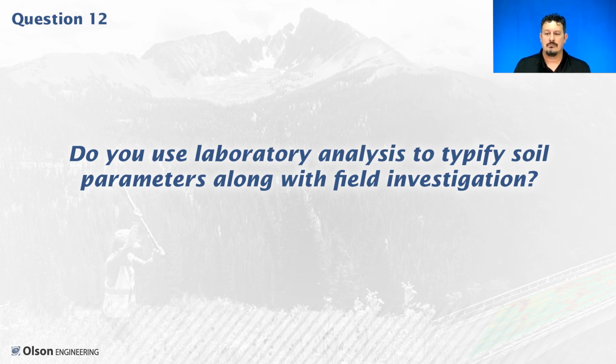Do you use laboratory analysis to typify soil parameters along with field investigation? Yes, I have spent a large portion of my career making lab measurements of soil properties for geophysics. The one thing to keep in mind is that it is essentially impossible to exactly reproduce the in situ conditions in the lab.